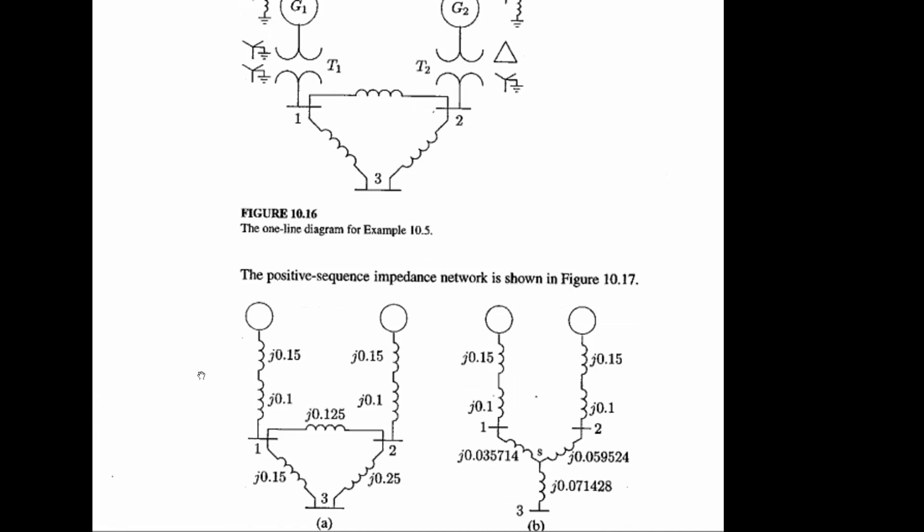Okay, this diagram. Earlier you could just call it an impedance diagram, but now you have to mention specifically that this is the positive sequence impedance diagram.